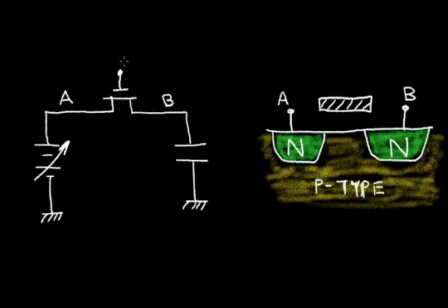Now when the gate voltage on the MOSFET is at a high voltage, in this case 5 volts, I'll form an electric field here, and I'll form a channel region. It'll cause conduction between point A and point B. Now when this gate is set at 0 volts, the switch will be off. I'll have no electric field, I'll have no channel in the NFET transistor.